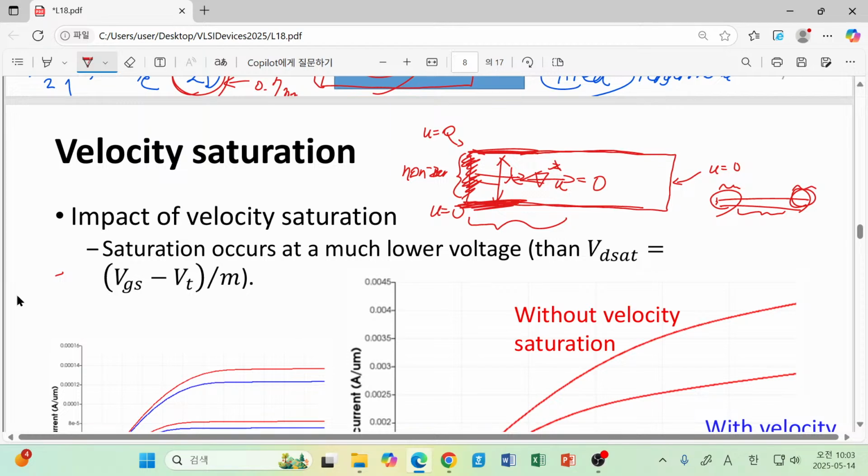If we are talking about a digital system, and we are currently talking about a digital system, it's completely okay. Nobody uses a long channel device. But the problem is sometimes we need to implement analog devices too. In the case of an analog device, our state-of-the-art device is not that suitable because it cannot provide a long channel device, and in the analog scene, a long channel device gives us plenty of advantages.